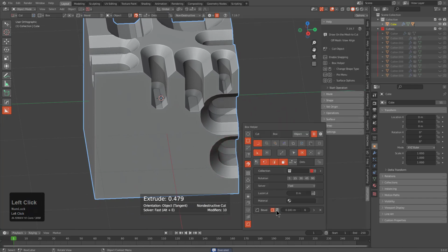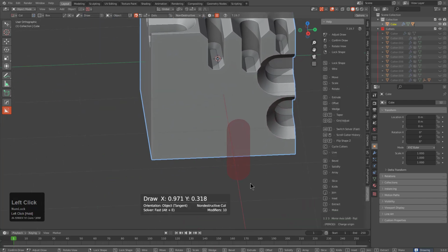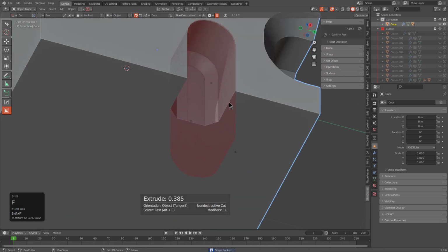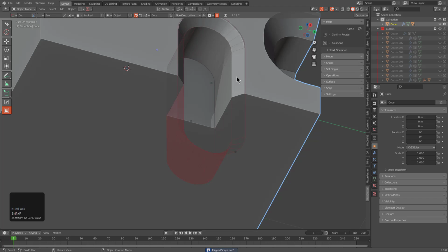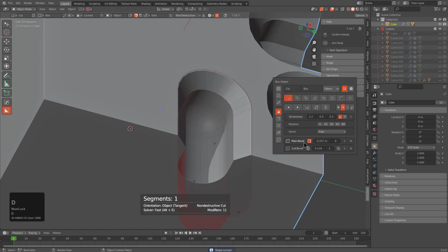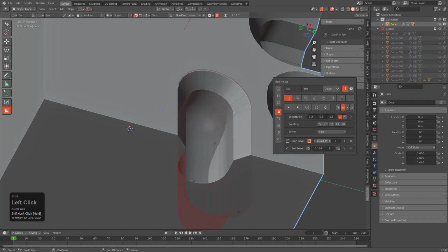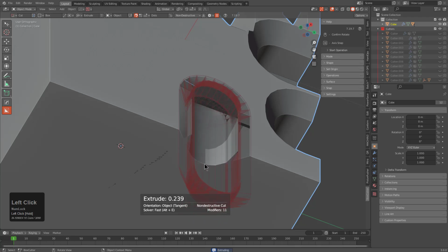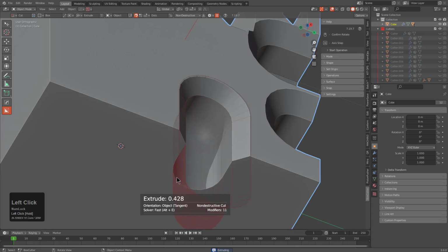So continuing on, let's just disable the bevel front face, which means that whenever I draw the shape, it's going to just have the Q bevel. In the event that I press Shift F, we have our reverse bevel, and if I press B, we are now using that first system I was talking about. So if I press D, we see that we have our main bevel and our second bevel, and this is the system that will definitely bring you into some issues if you're unaware of its existence. So like I'm saying, this is something we're definitely looking into resolving, but it's part of a very deep discussion that we're having currently about bevel that still continues to this moment.